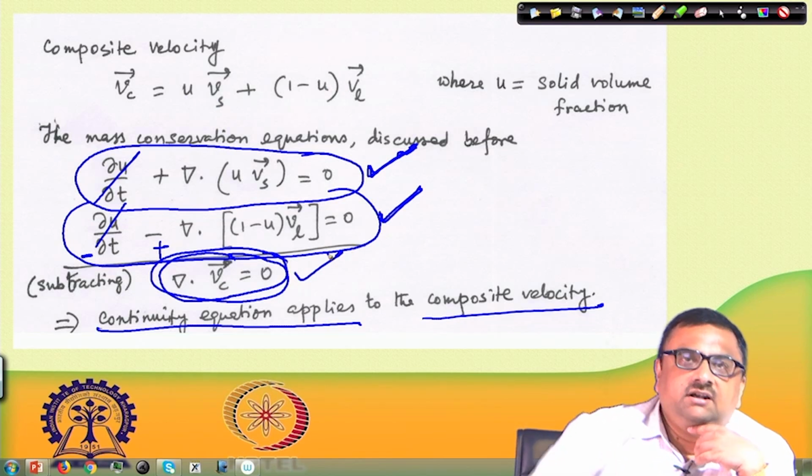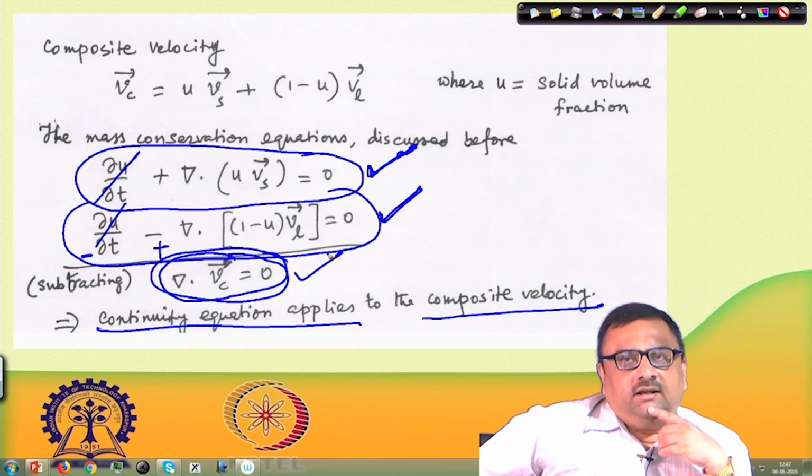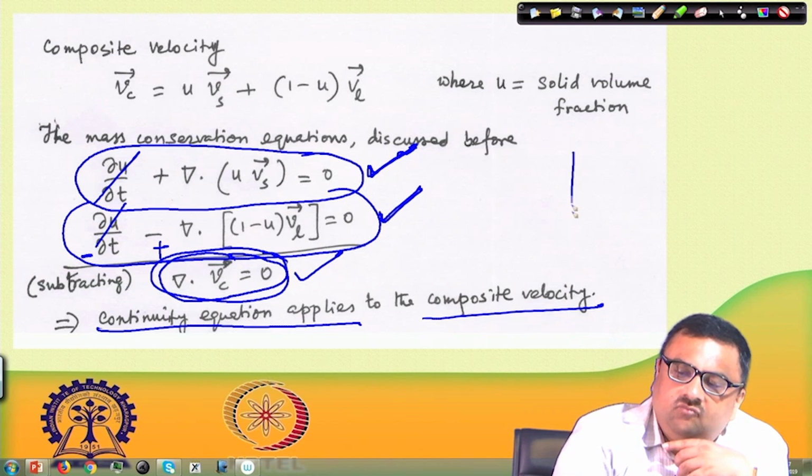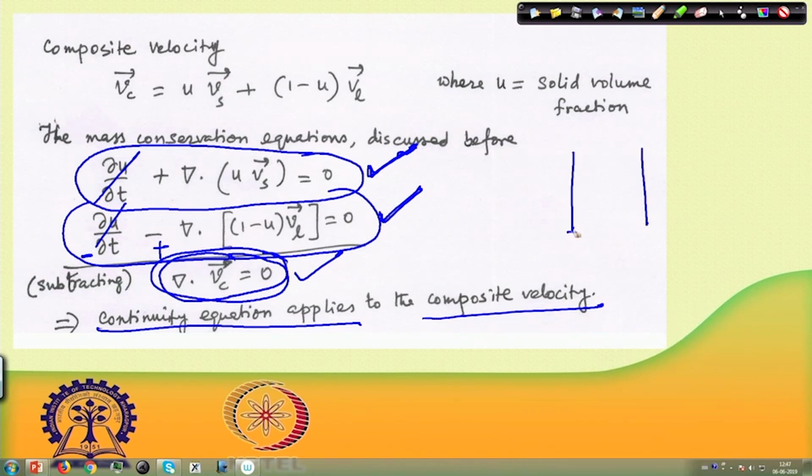So this continuity equation applies here, and it has a very important implication. If we are talking about a one dimensional problem, where solid and fluid are getting compressed, then the equation becomes del V c del x equal to 0, so V c is equal to a constant. V c becomes invariant over space.